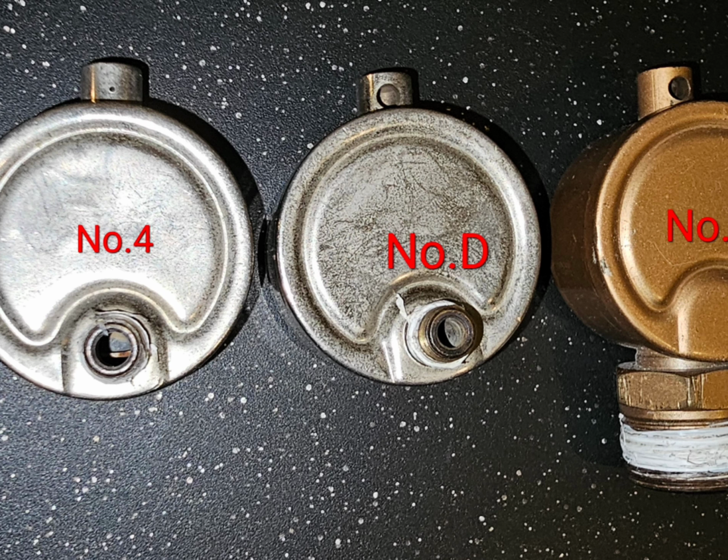Gordon number 1, I primarily recommend using these on steam mains, at the end of a steam main preferably, or at the top of steam risers. These should not be used on steel convectors, aluminum convectors, or any type of convector that is not cast iron based. And even with a cast iron convector, I don't recommend that you use them either. If you have no choice but to slap it onto a cast iron convector, I recommend that you only do it for temporary usage and replace it with a new valve at the first chance you get.